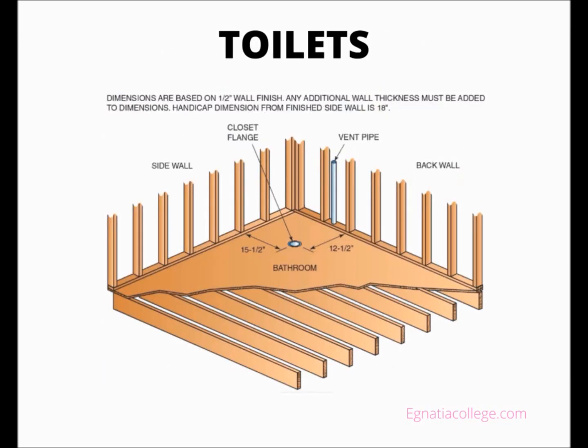Toilets. The most common kind of toilet installed in a residential home has a two-piece design, with a separate tank and bowl. Some custom homes install one-piece toilets in the guest bathroom and the master bathroom. The two toilets have different water supply requirements, but the drain connection remains the same for both. The two most common rough-in dimensions for drainage piping are 10 inches and 12 inches from the back wall, but 14 inches might also be used for some toilet designs.